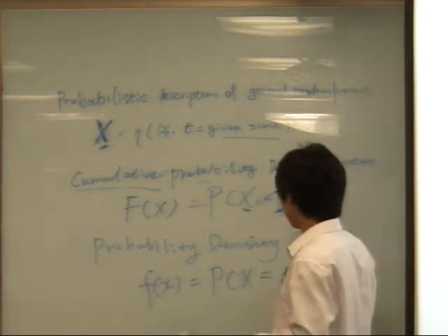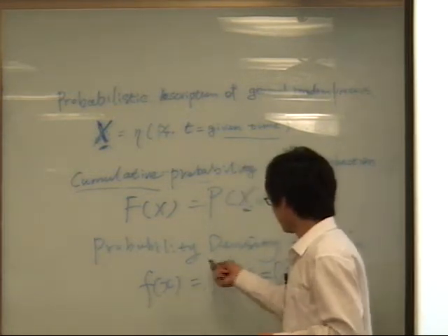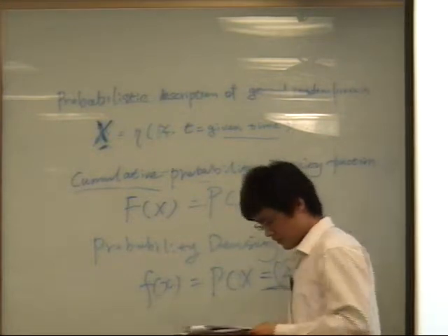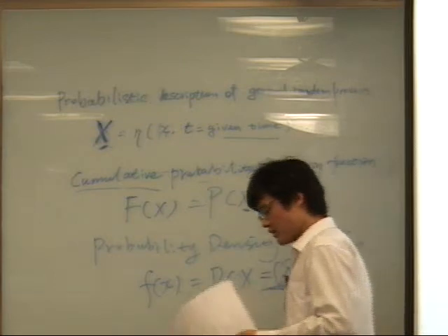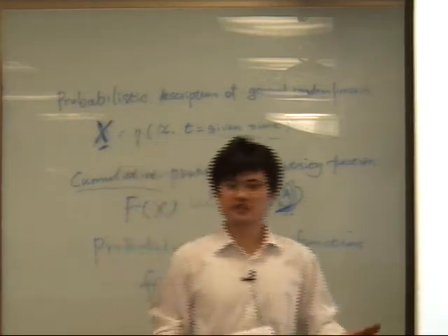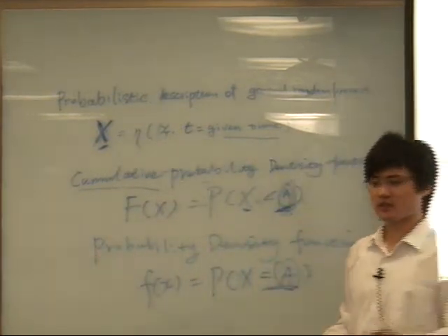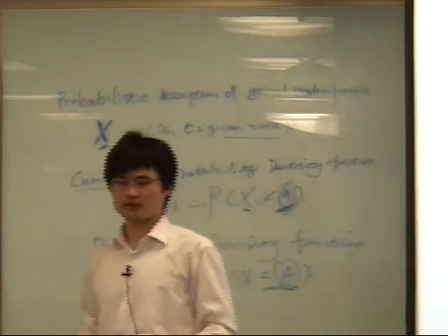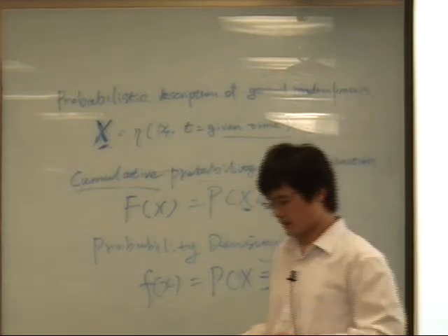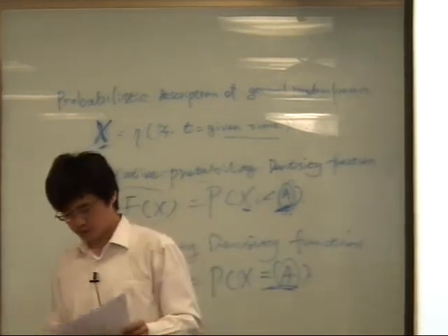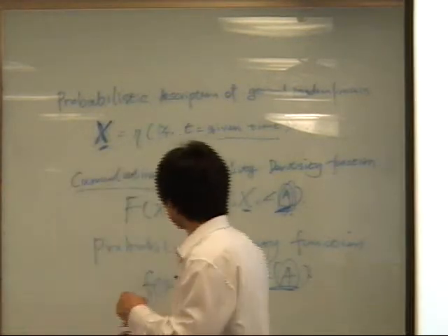And this one is the probability that it equals this one. Why are we looking at this? Because later on you'll find the surface elevation in the sea follows a normal distribution, while the amplitude or wave height follows a Rayleigh distribution.